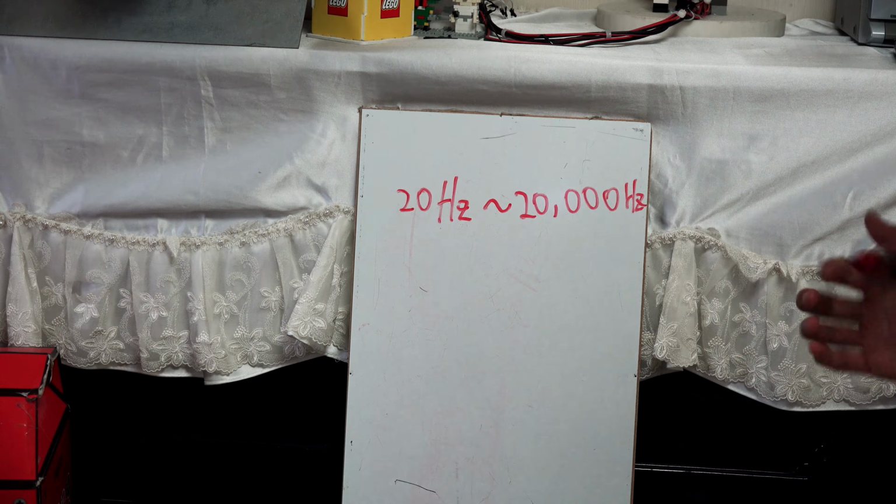But there is one problem, because this ultrasonic sensor shows the duration of going and coming back. So we have to divide it by 2, so we can find out how far it just went.